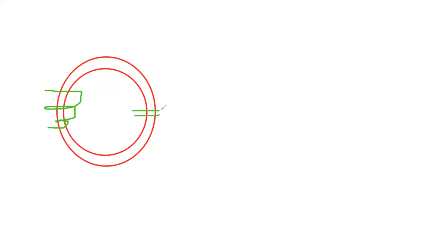So we add an air gap of 2 millimeter in this ring. Here, of course, we keep the same current, and we add an air gap. After adding an air gap, it's like we add a new resistance.